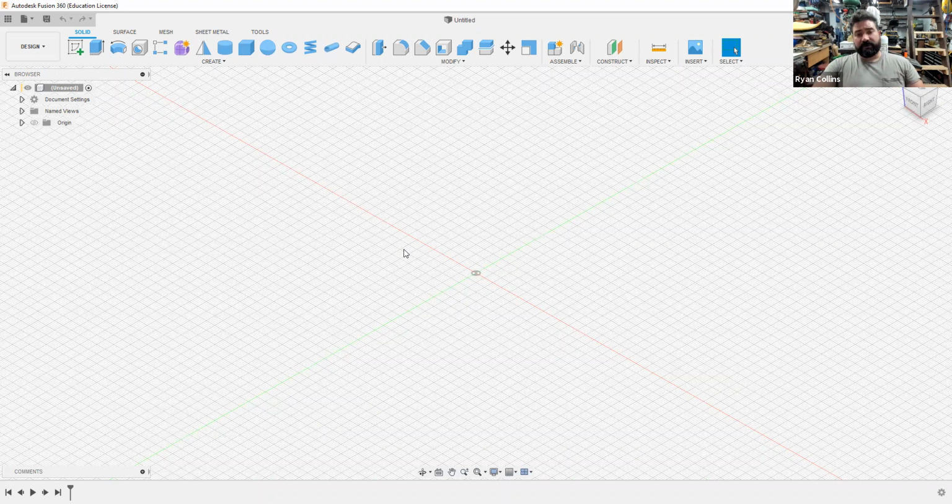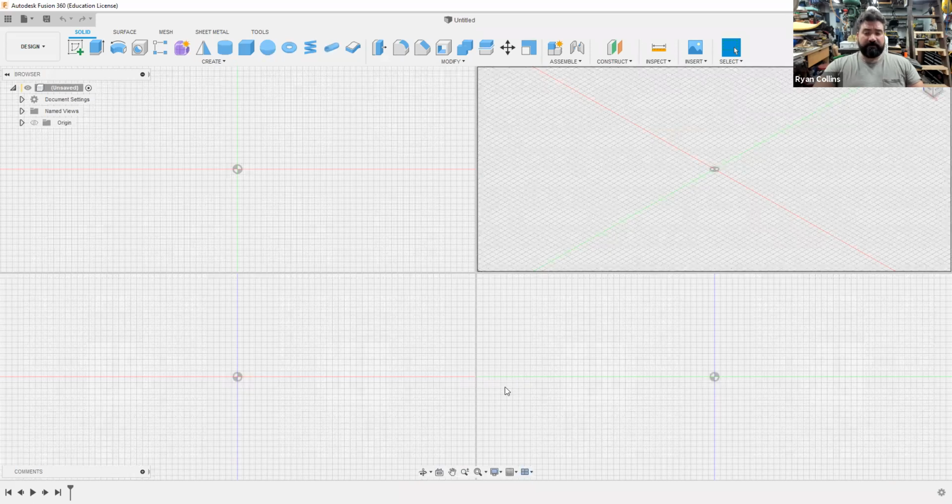Like I said, if you are used to other viewing methods, like the more standard drafting or CAD design layout, if you go to the center buttons down the bottom, Viewports, Multiple Views, or press Shift and 1, that will shift between your standard 4 different views.